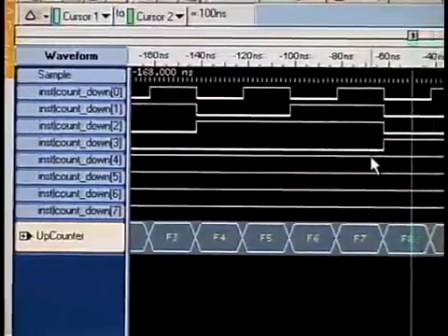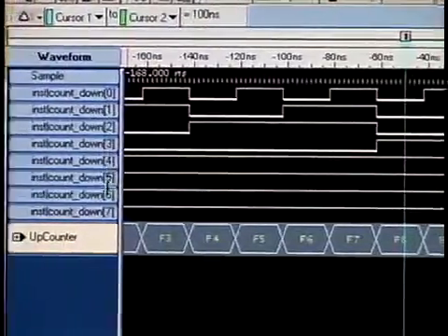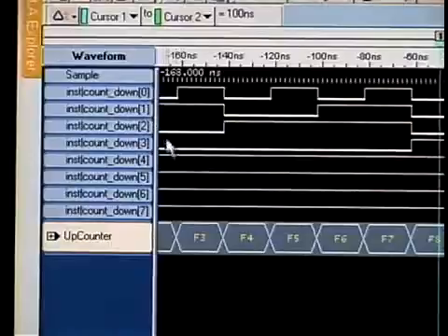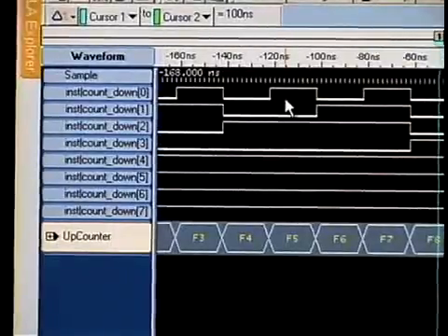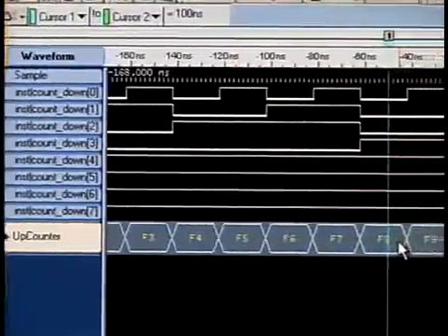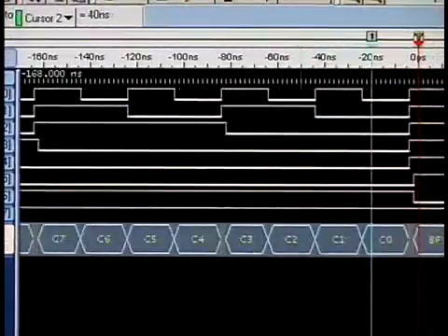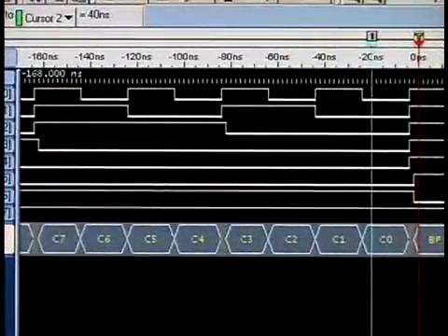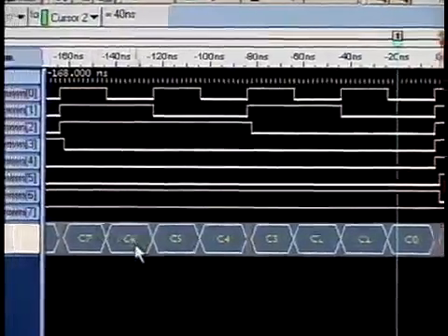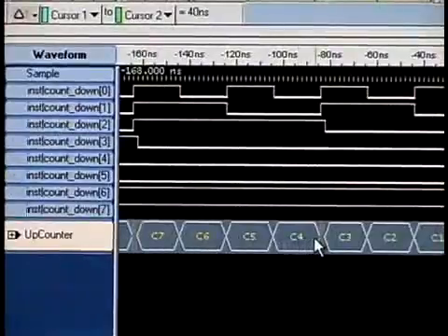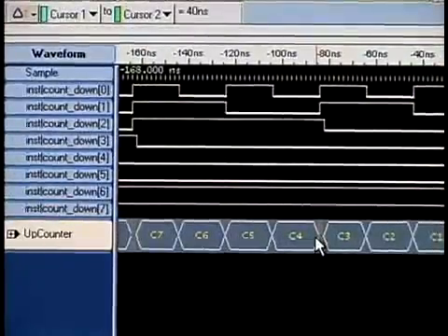They're still on screen, and yet they've been renamed with new label names. So I'm showing incorrect data here. I see the up counter. If I press run, it should switch the mux inside the FPGA and then capture these down counter signals. And sure enough, I can see C6, C5, C4. It's counting down.